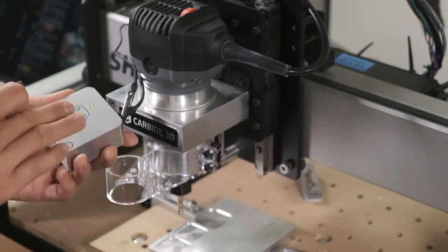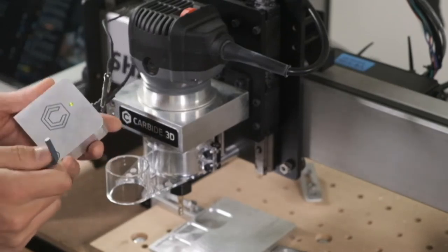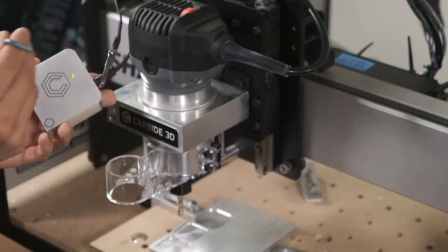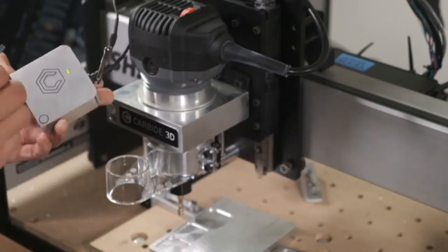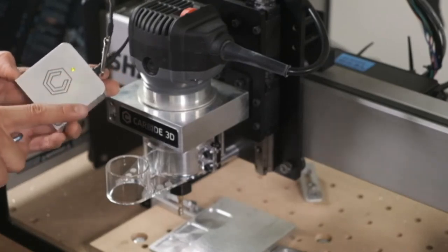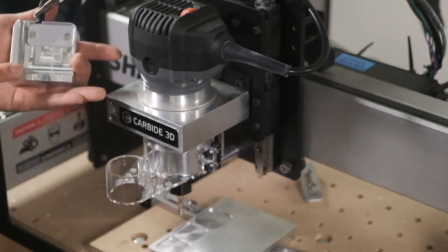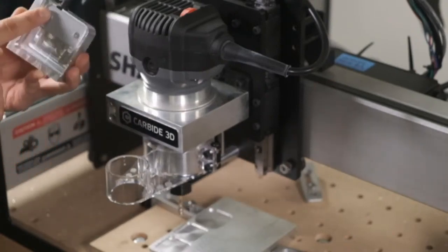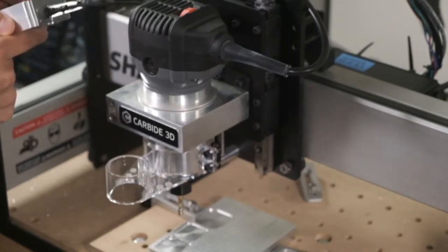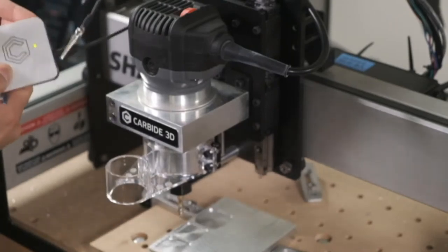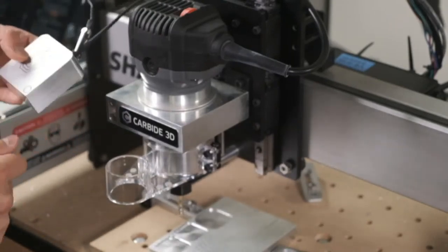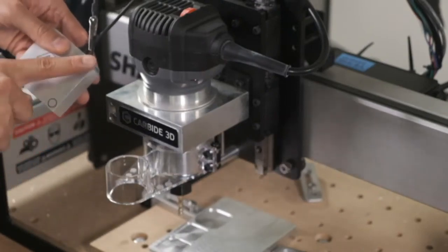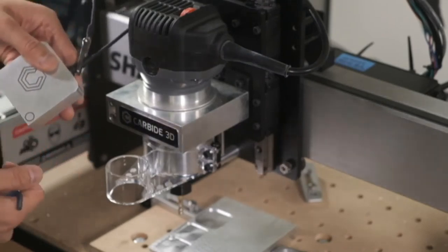If you're only probing Z, it can basically touch anywhere because this whole surface is theoretically coplanar. But I would recommend that you touch in this half of the bit zero because this is your contact area. So if you touch out here where it's unsupported, you're going to get a little bit of tipping. And that might not give you an accurate result, even though in theory it should. So just keep any Z probes on this half of the bit zero.